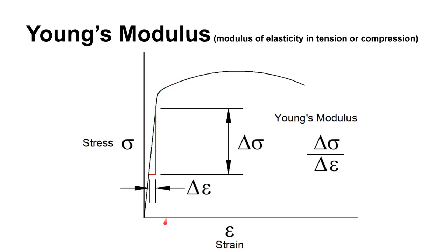to do is put this into Excel at some point. We'll do this for a lab, and you'll see the data, and you'll see where you can get good values for stress and good values for strain. And like I said, there are different ways of determining, of actually doing this calculation. You could find 2 points on here if you wanted to, or if everything is properly calibrated, you could use 0, 0 as one of your points and just find any arbitrary stress and any corresponding strain value and just divide those two, any data point on here.